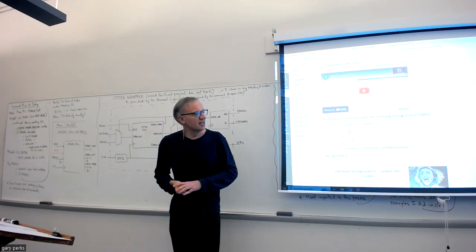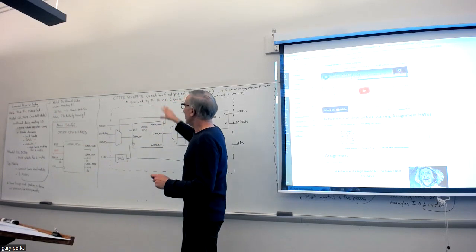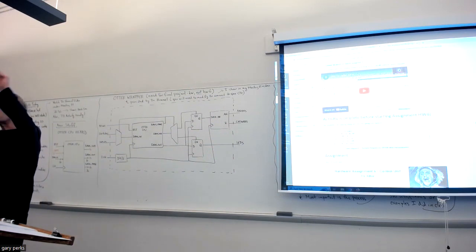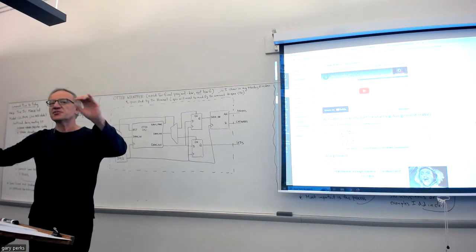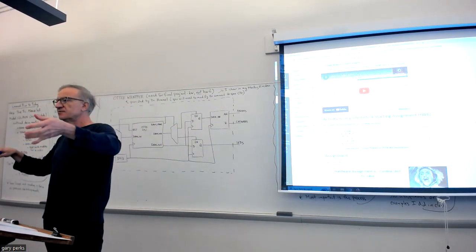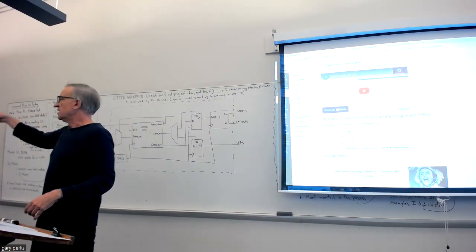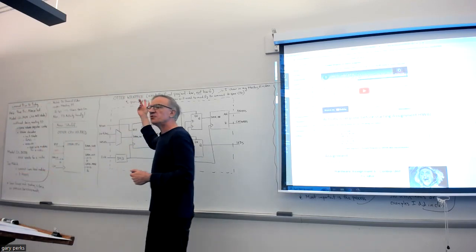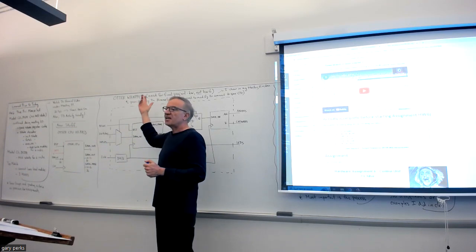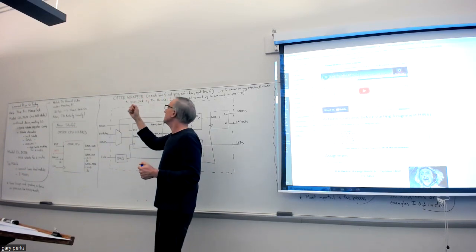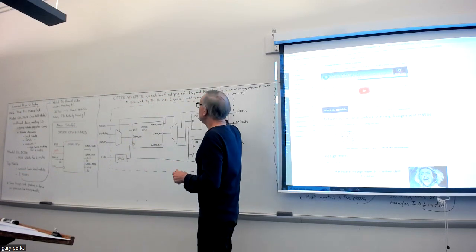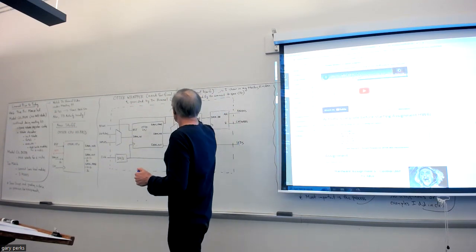The next thing that I want to talk about is the Otter wrapper. The Otter wrapper is circuitry that goes around your CPU, and it interfaces the Otter CPU to the outside world. So it's going to interface it to input devices like switches and output devices like LEDs and 7-segment displays. Dr. Hummel provides the Otter wrapper. He designed this. Now, you'll most likely have to do a little modification to it that I'll get to in a little bit. But this is what the Otter wrapper looks like.